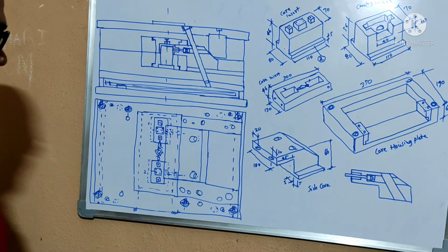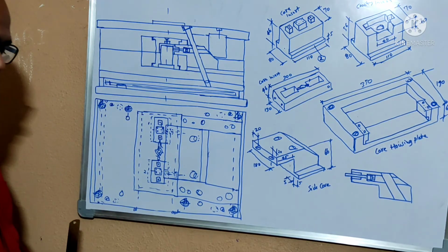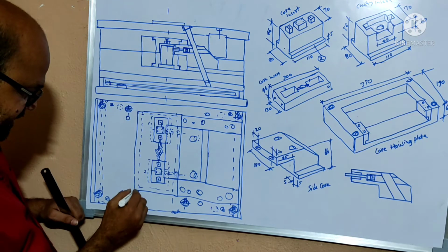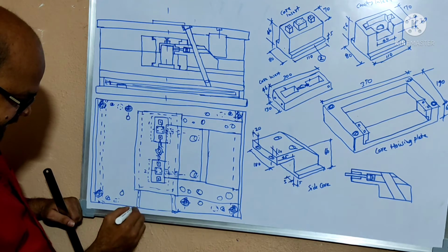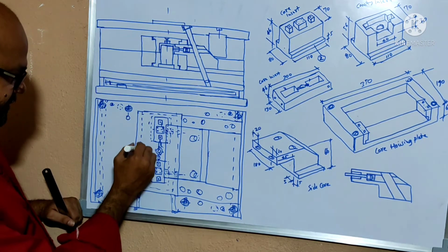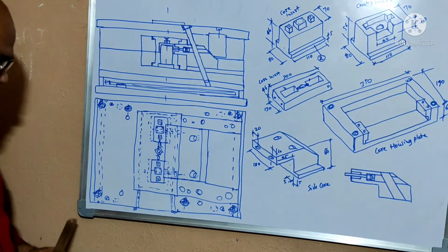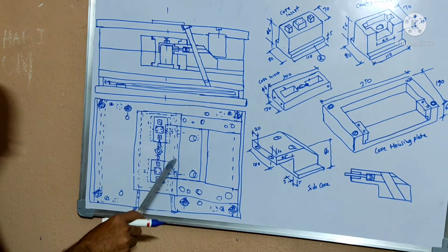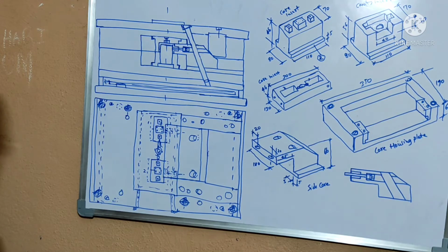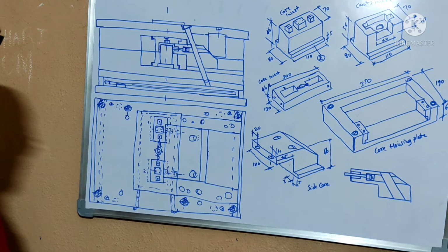Similarly, this tool, when you observe in the top view, the cooling circuit is a rectangular cooling circuit. What I had used here, from this one, from here, here and this one. Here from this side the cooling circuit moves, and from this one the cooling circuit will come out. Means the water has to move from this end and cover this one, and it goes outside. This is the rectangular circuit, or you can make it as a U circuit also. That's no problem.